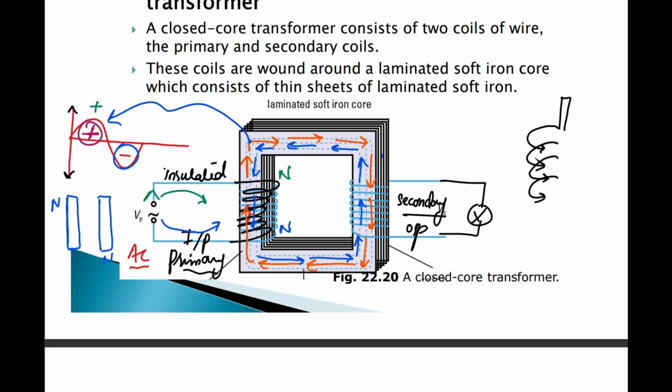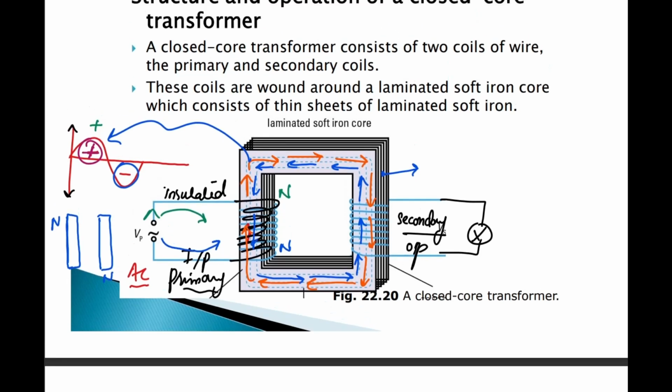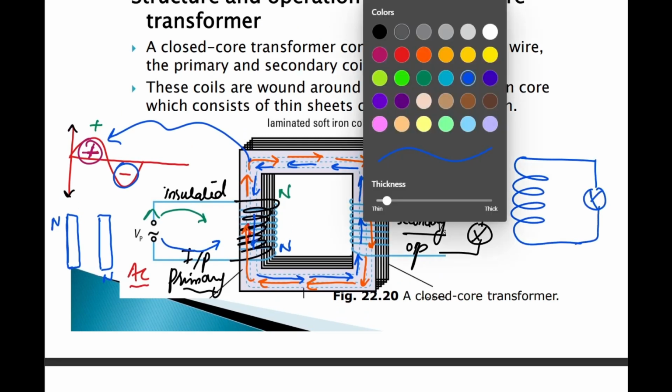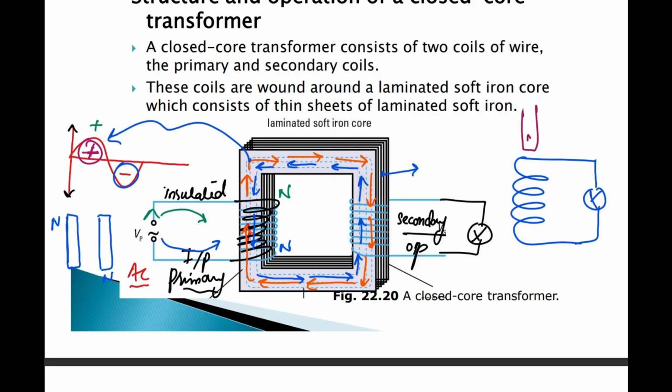So if I analyze this one side of the transformer, what has effectively happened with the secondary coil, which has the load, no supply, no power availability? You see, if this is my coil and I connect a load with it, in Faraday's law we introduced a mechanical magnet motion ourselves to see an induced EMF. This time around, we are doing this by an automated method. The coil is experiencing changing magnetic dipoles through the iron, so it is as good as changing magnetic flux.